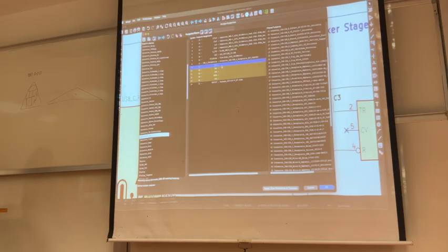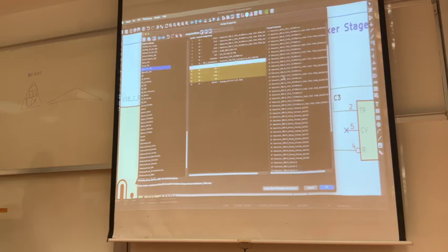And for the resistors, I'm going to pick one and go with the other ones as well. R1. I come to resistors here. SMD, as always. I'm going to use SMD components for all of it, except LED and the receptacle and the main IC. And resistor SMD R1206, hand solder. And I'm going to copy it and paste it across all of the resistors.